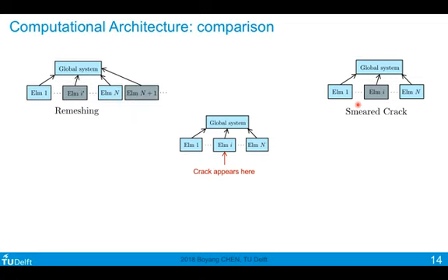In remeshing, however, you delete the original element I, and you replace it with a bunch of new elements. So these elements would have different nodal connectivities from the original element, and of course you have more elements in total, and your system needs to be adaptive enough to take in all these new elements. Your problem size would grow larger and larger as you have more and more elements.